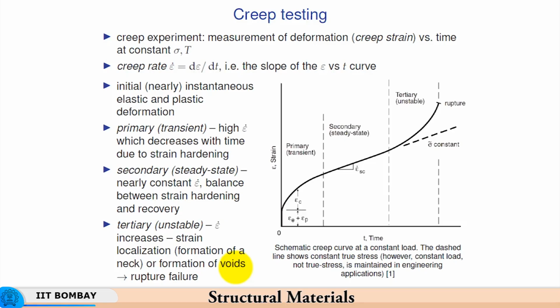Of say constant strain rate operation, because that constant strain rate operation is macroscopically constant. Internally, you might find that the non-uniformity in strain has a strain rate, and therefore tertiary creep has set in much earlier than what was discovered macroscopically. So, that is the reason why in the tertiary phase there is localization taking place, then there is internal coalescence of the intervoid ligaments taking place. So, these are events which finally contribute to the rupture of the deforming materials under creep conditions.